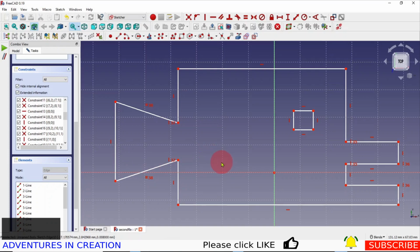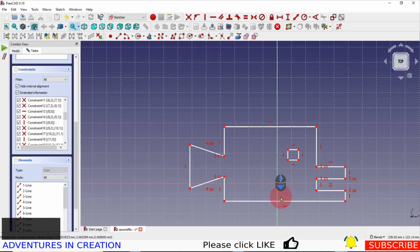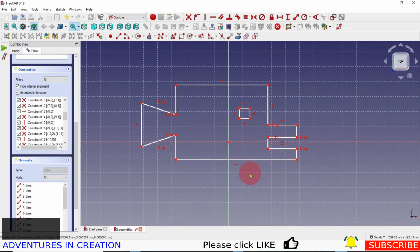Now what we're going to want to do is set up a center line between here and here, or we can move the whole model down so that it all centers here. And to do that, we have to be a little bit careful that we don't cause symmetry here to pull everything down and destroy our geometry. If it turns the geometry inside out, then you're basically going to end up redoing your geometry.